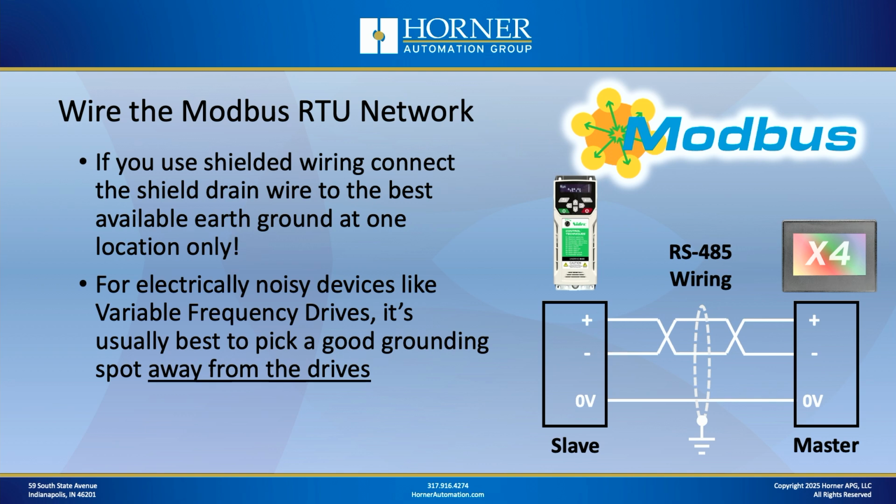And also, another tip, if you happen to be communicating with variable frequency drives or other devices that are electrically noisy, it's usually better to ground the shield away from that noisy device.